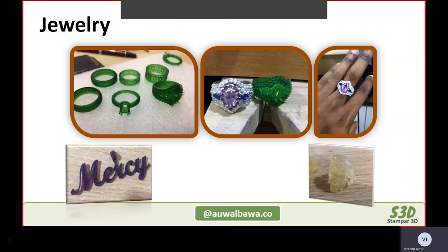Okay, so with jewelry now, this technique is presently being done in Nigeria, where you can make very, very custom jewelry. How this is done is you will use a 3D printer, maybe using wax or something as a raw material. We'll use it to make a very precise version of the end product, which in this case is a ring of our chosen design. And then we create a mold around that, and then pour in our metal. So pour in molten silver or molten gold.